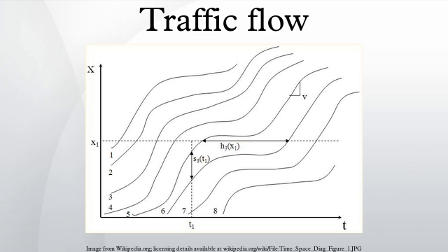A spontaneous traffic breakdown occurs where there are free flows both upstream and downstream of the bottleneck before the breakdown has occurred. In contrast, an induced traffic breakdown is caused by a propagation of a congested pattern that has earlier emerged, for example at another downstream bottleneck. Empirical data that illustrates the set of fundamental empirical features of the traffic breakdown at highway bottlenecks, as well as explanations of the empirical data, can be found in the Wikipedia article Kerner's breakdown minimization principle and in review.